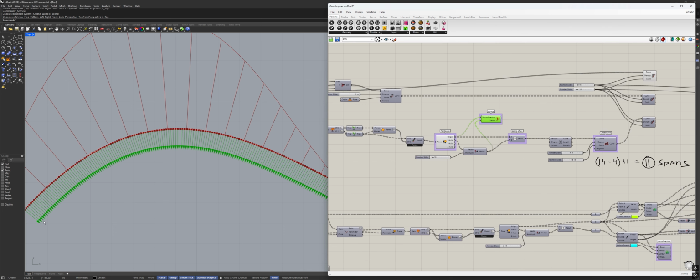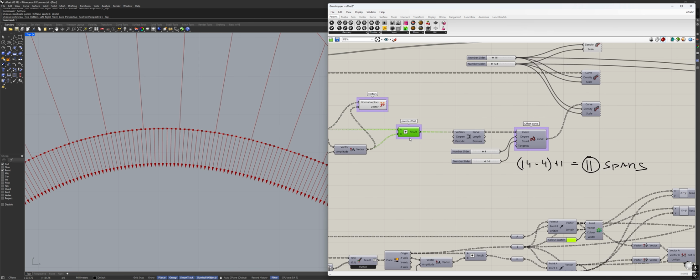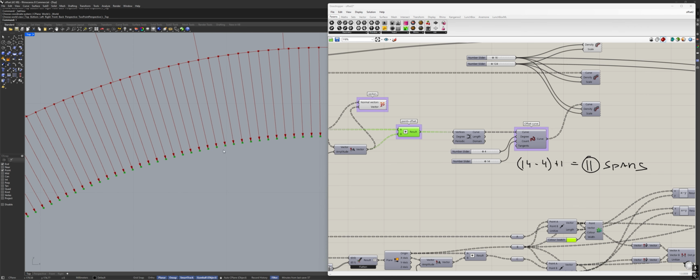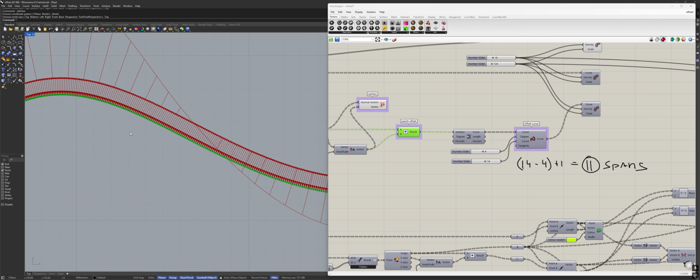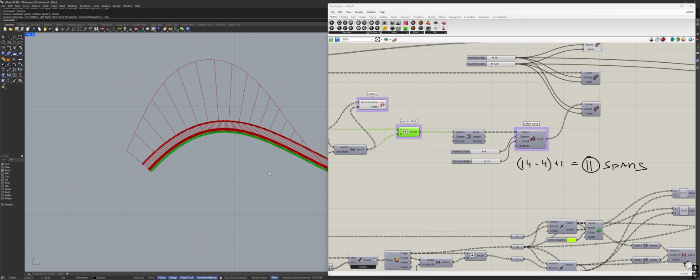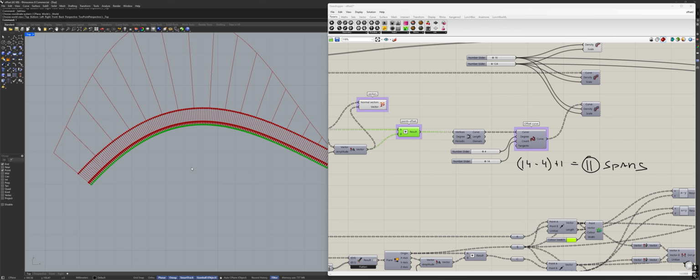After that, Alias will construct points on the ends of these vectors. So it basically adds up the coordinates with a scalar value, and then it will get another corresponding pair of points. So for every point on the original curve, there will be a corresponding point in the normal direction at a specific distance, right? And after that, Alias will reconstruct the curve. Now, my script, of course, works very basically, so I'm defining how complex the curve will be. Alias does it itself with a lot of other constraints, but eventually you will get the line.